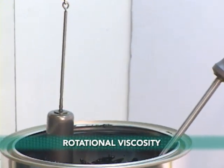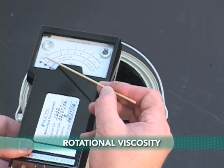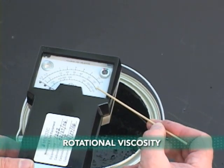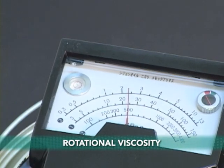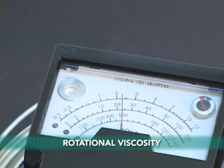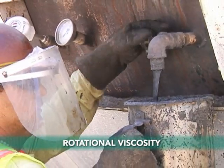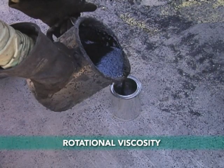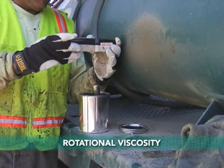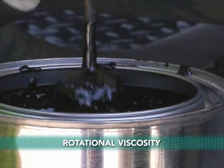Rotational viscosity is the go-no-go field test that governs use of the asphalt rubber binder. At least one viscosity test is required to establish compliance for each asphalt rubber batch and holdover load. A sample is drawn from the reaction vessel through a spigot into a metal container. Measurement is determined by a rotational viscometer and presented in centipoise.